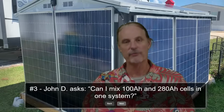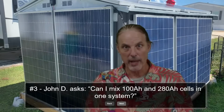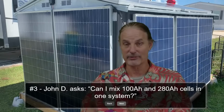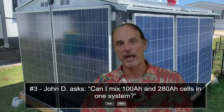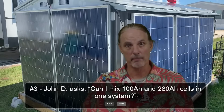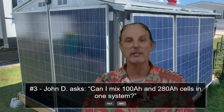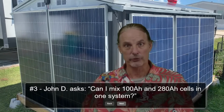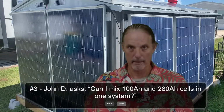In other words, if you hook up 4 12-volt batteries in series to create a 48-volt battery, then you do have that power flowing through all 4 of those batteries. And if the battery is not designed to handle that, it could cause problems. Most of them will also tell you that you can only have so many in parallel, and the reason for that is the same thing. They don't want to see that transfer of power from battery to battery cause the BMS or cause issues there. Thus, my reason for everything needing to be appropriately fused to keep them isolated and safe from all the other batteries, and assuming that you did turn it on in a situation where you weren't supposed to, you would like to lose a fuse, not a battery.